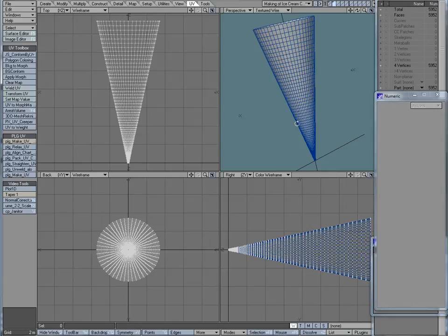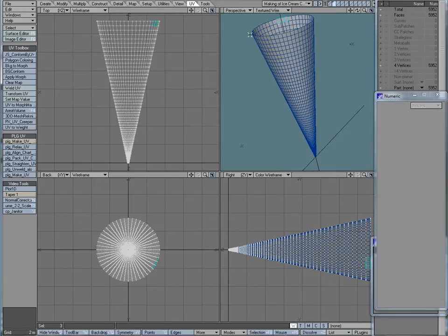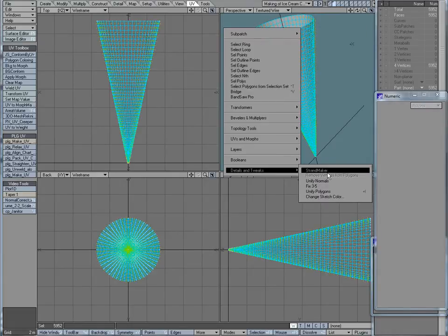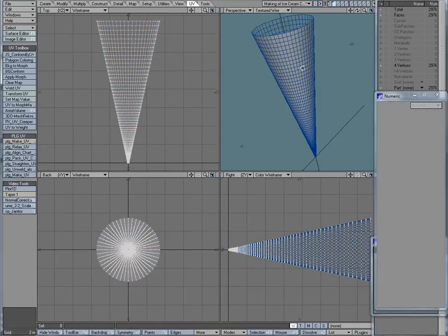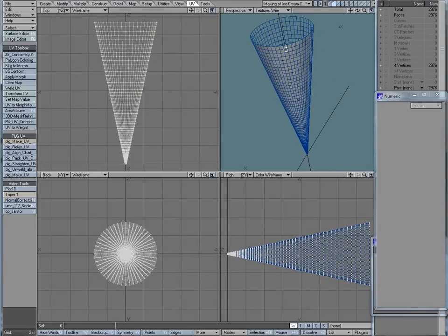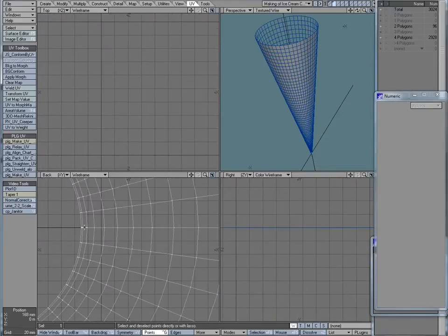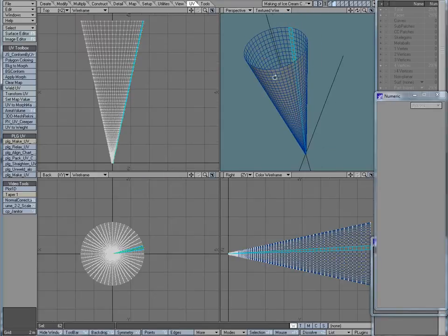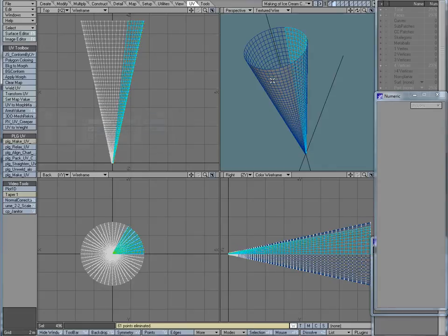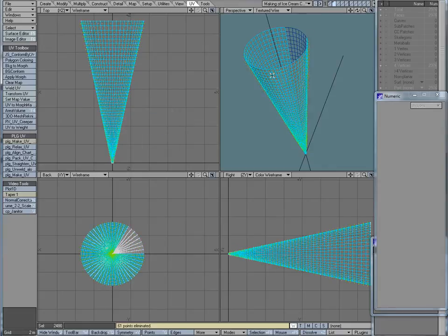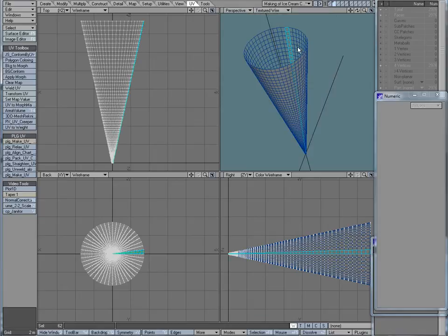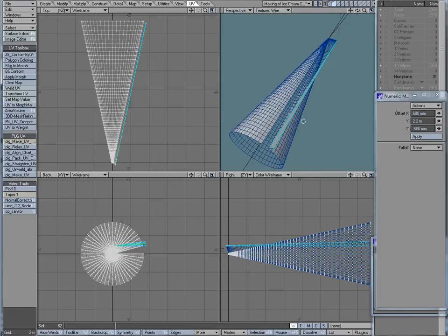I'm gonna make the seam, so first I'm gonna get rid of duplicated polygons, so 5 polygons. I just get one side, and now for the seam, come here, loop and weld. Select the loop here and extend selection, merge, and now I got a nice opening here.